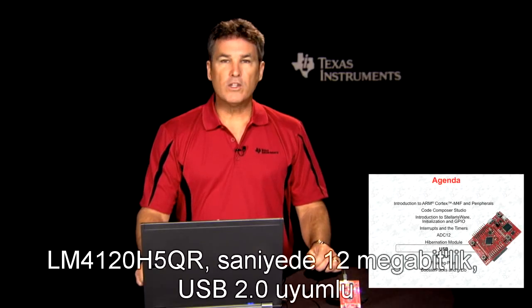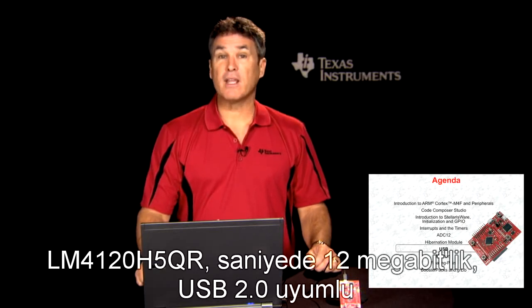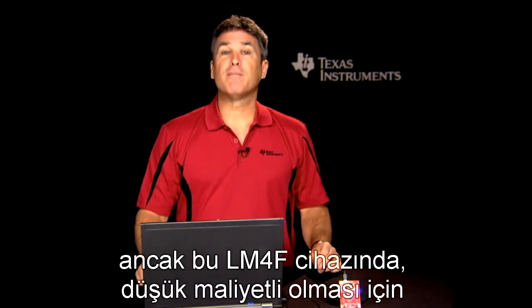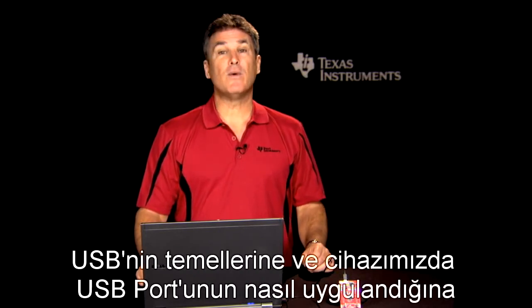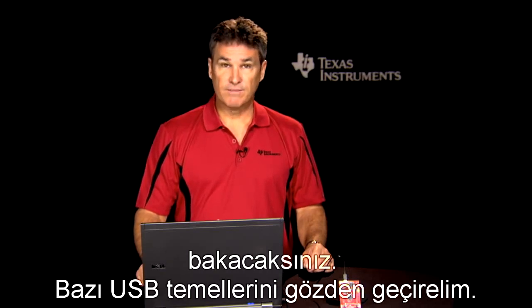The LM4F120H5QR is equipped with a 12 megabit per second USB 2.0 compliant USB device port. USB ports on other Stellaris devices have on-the-go and host modes as well as device, but this LM4F part is cost reduced to have just the device port. In Chapter 6, you'll look at the basics of USB and how the USB port is implemented on our device.